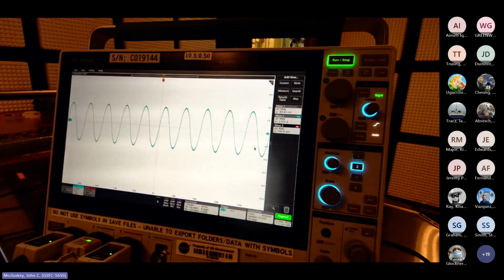Okay, now our current's about 2.522 amps. So the current's going down a little bit. Now that's not such a bad thing if your short circuit current isn't quite at 4 amps. It may mean you're getting a little bit of an undertest. If you're going into a low impedance, you're not going to get quite as much current as you might think you would. But at least it's keeping your hardware safer.